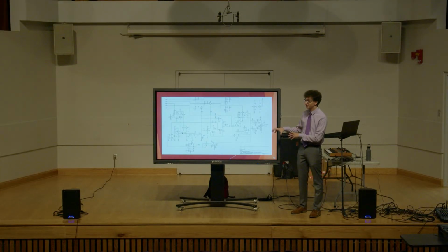It's essentially the same thing with that minor fix, but I've also implemented mixing between the inverting and non-inverting modes, which I'll show you in a second, and then a Schmitt trigger inverter from an op-amp to take feedback from the output for the looping mode. So when the output goes high, the inverter goes low and turns off the input. So then the output starts its decay phase. When the output goes low, the inverter goes high, turns on the input, and it starts the whole loop over again. So in that way, it's looping.